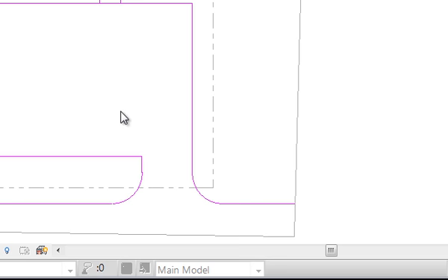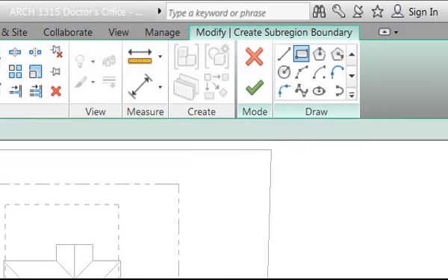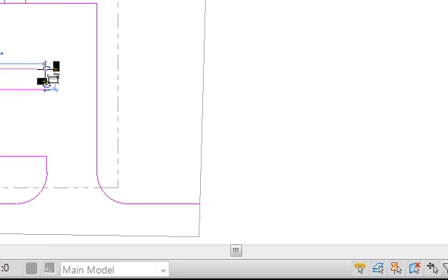So if you have a median, you know what a median is? Like in a parking lot, sometimes there's a curb with trees in it, like a little break in the parking lot. You understand what I'm saying? So if you had that, the radiuses would be 2 feet. So I'll just draw a quick one here. Again, you need to be careful and dimension all this out. I'm just trying to show you the steps involved, I'm not dimensioning it correctly.